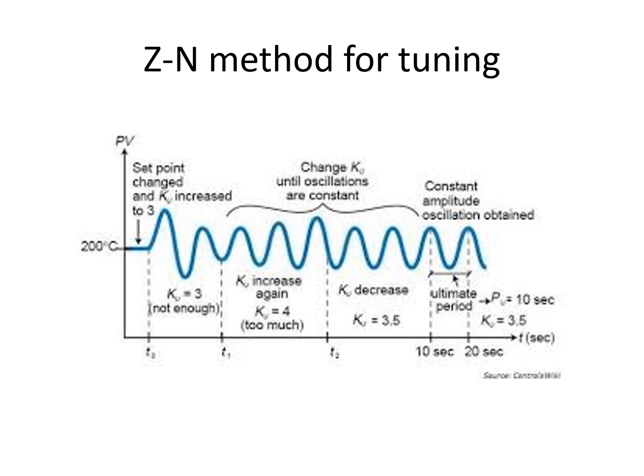This is an example to show you the different types of oscillation. You increase your Kc until you get some sort of continuous oscillation going through here. And from here you get what you want. Basically the two basic parameters that you need are the ultimate gain, Ku, and the ultimate period. Once you have the Ku, the one that gives you the continuous oscillation, you then get your ultimate period. This is used to tune the controller. Of course, you apply a certain set point change.